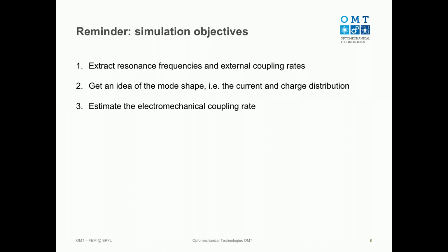So the take-home message is that multimode circuits are obviously the future. You should simulate them, because if you don't simulate them, it takes a lot of time to fabricate and to measure, and you'll be very disappointed. What's important is not just to simulate parts of the circuit and then say, okay, I know everything, I put them together, it will work. You should simulate the parts and then the whole thing. And I showed you this case study, which is two microwave modes coupled to one mechanical mode. And here you see that this hybrid mode design is the ideal one.